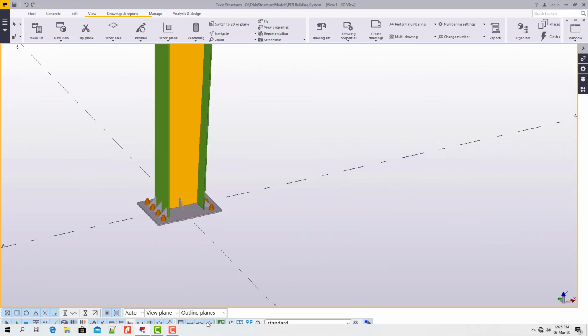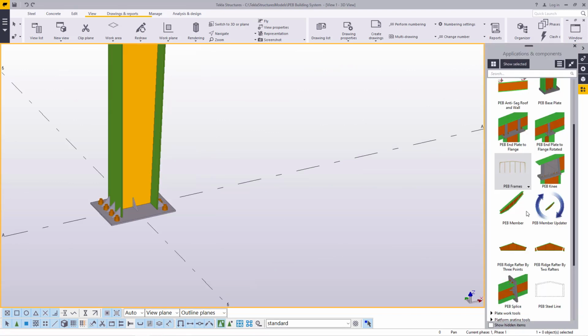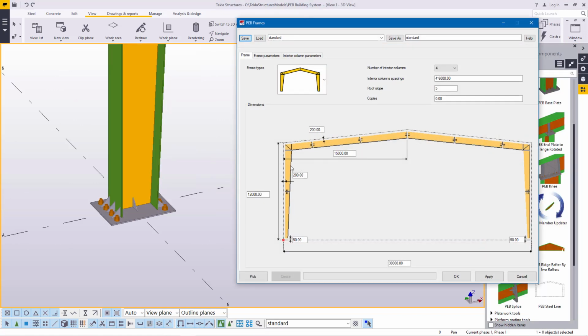So whatever I did, if I come back here and double click on this, since here we have 600, and the bottom end here we have 300, I just fed in the half of the bottom taper of 300, which is 150. So I prefix that half of 300 by a negative sign, so that will pull it right to the center of this.